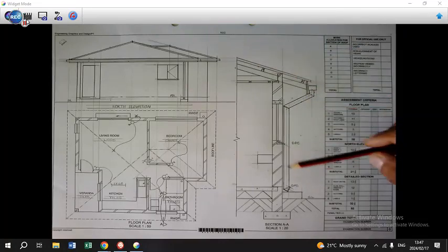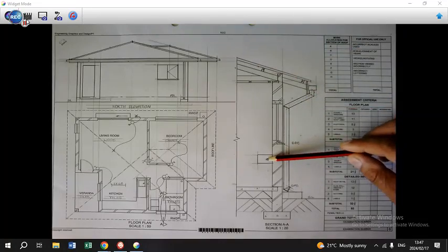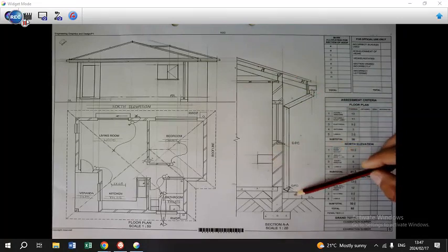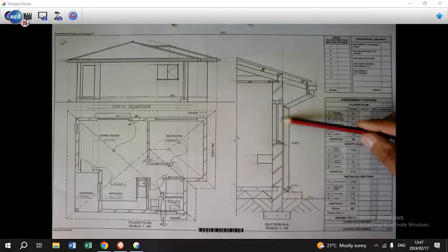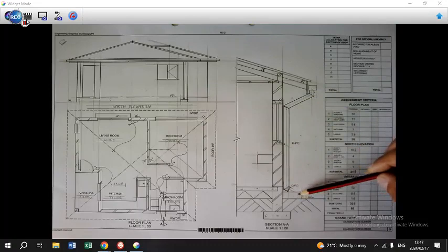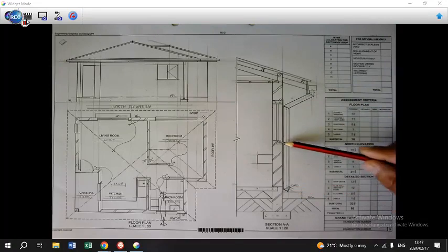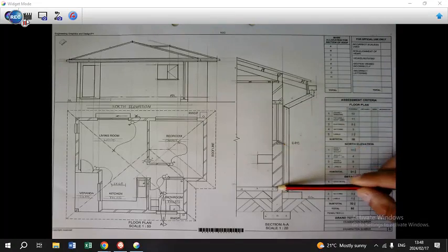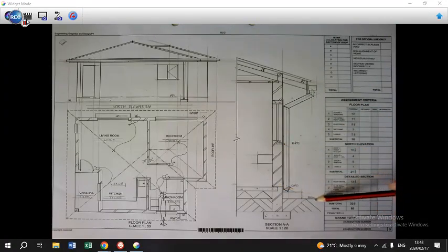And then of course the little detail of the wash basin in the backdrop, as well as the gully where the water is going to filter in from the gutter through the rainwater downpipe. Add in your labels. DPC will be here, DPC will be there, and your ground level will be on this level over here. That concludes our entire civil drawing in detail.